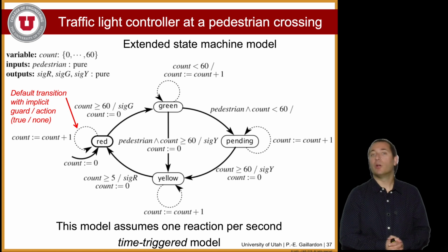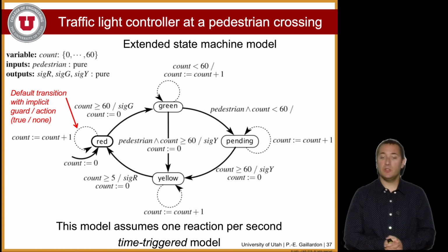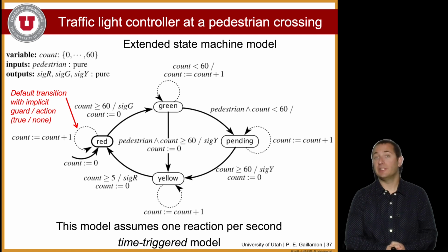One last thing that is important to consider on this finite state machine, it is a time-triggered model. This time-triggered model will react on a tick of a clock, which will be linked to the counter. The counter will count time, the number of ticks in that particular case.